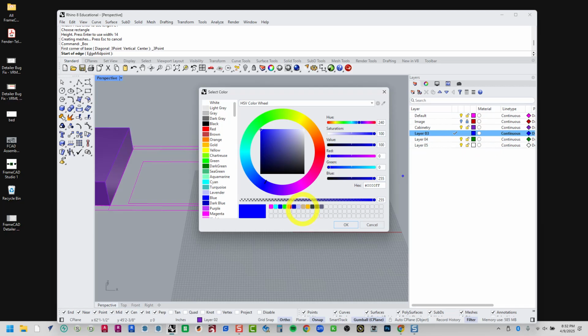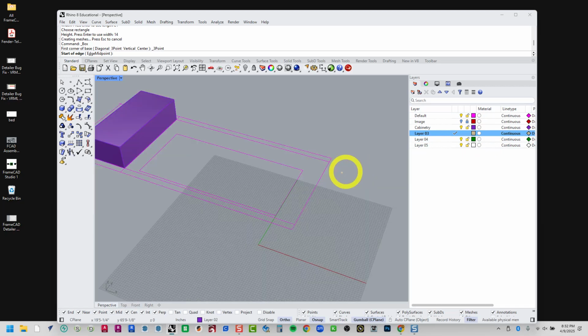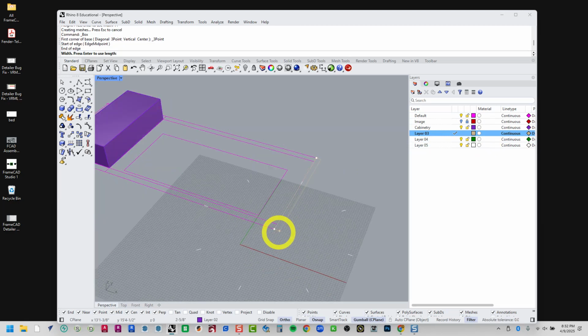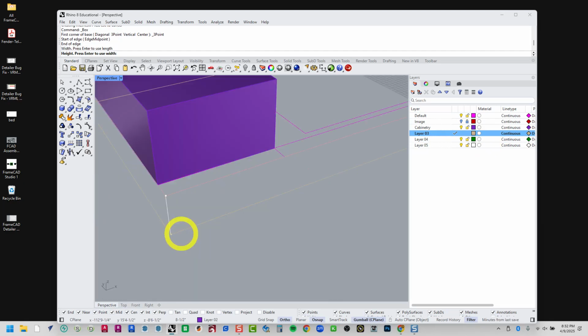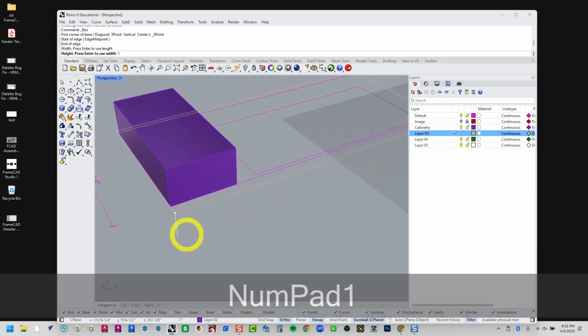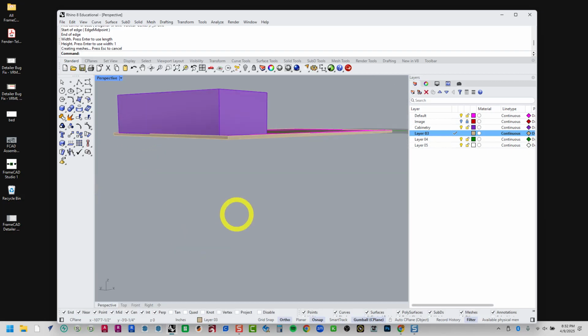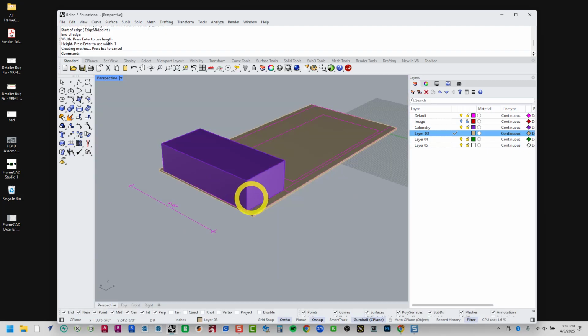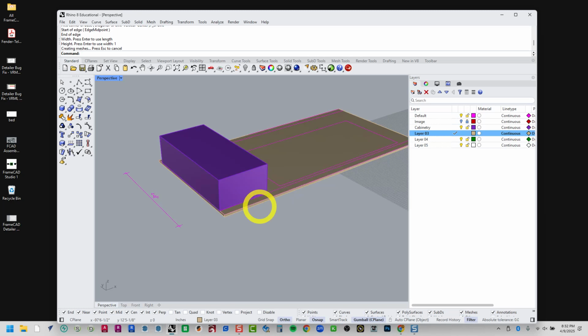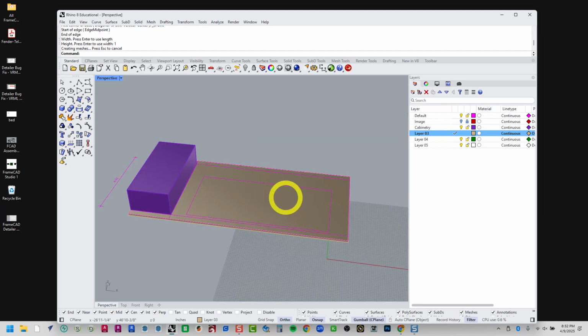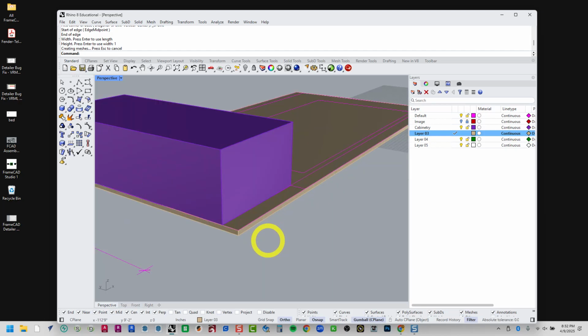Did you go negative on 3? I did. Okay. Good catch. And yeah, so the 1 inch plywood that I have here, if I go to shaded mode in all 4 of my viewports, that plywood is sitting below, basically in the negative Z direction. It's sitting below this Z0 value. So it's sitting beneath my 2D drawing, yes. And if it hadn't appeared that way, I would have just moved it down 1 inch to make sure that it's below my drawing. But yes, good catch.